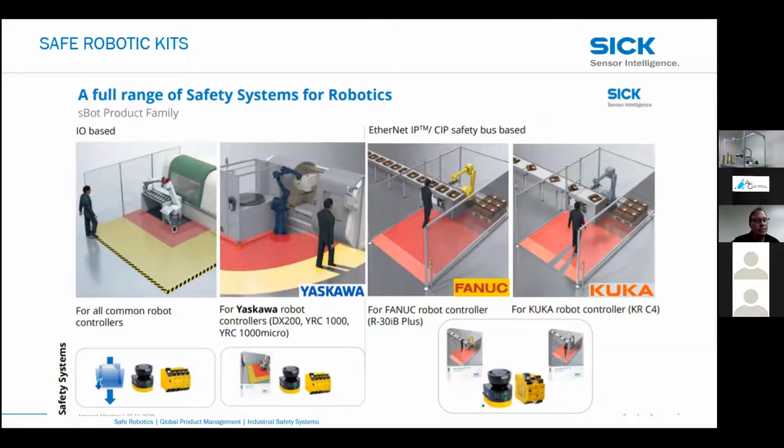So what we are hooked up to here is an Omron robot, very nice Omron robot, and we'll talk about that. I used an Ethernet/IP safety Safe Robotics system, and then I modified the outputs to give them dry contacts to do their slowdown and pause. So that's the beauty of these systems. You can take one and then they're freely modified. We don't lock down the software.